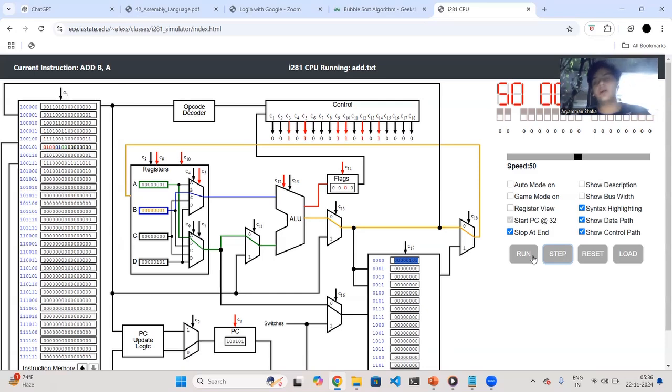Something I forgot to mention here is that in this break if greater than, you move to the end line of the code. Essentially what that does is you add some value to the program counter which gets you to that line.